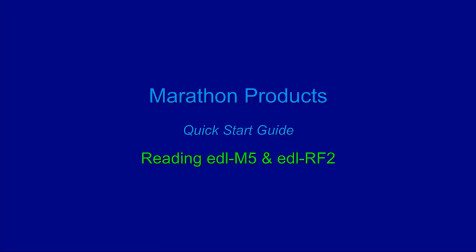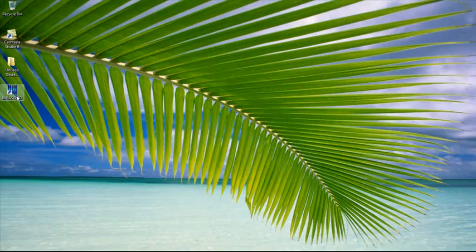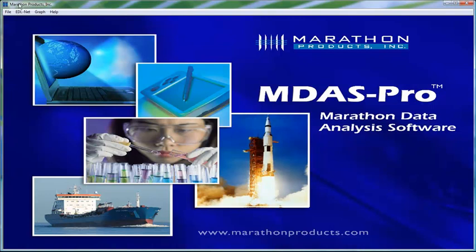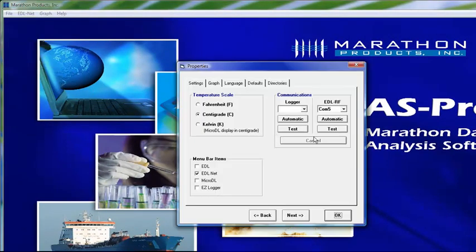This is the quick start guide to show how to read the EDL-M5 and the EDL-RF2 wireless devices. You start the MDAS software by double-clicking on the icon on your desktop. You go to File and select Preferences from the drop-down menu.